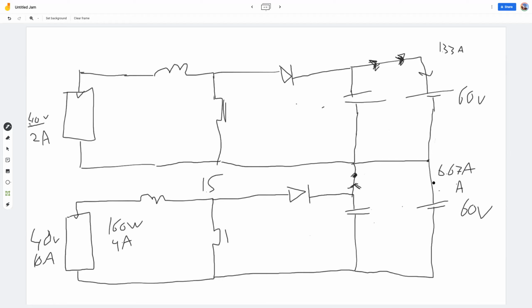What you can do is connect a converter here that transfers energy from the top half of the battery to the bottom half of the battery. But now you have an extra converter again, right? Now you're basically doing the same thing that the MPPT system was doing, but on the output of the MPPTs instead of the input of the MPPTs. So that's not ideal either, right?